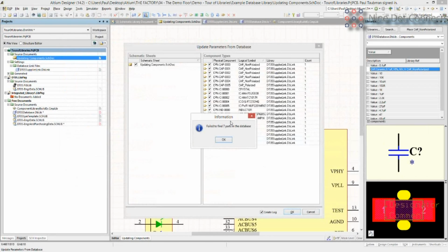The other 6 of them were resistors because my database library that I linked this to came from DigiKey. I don't know if you guys know this, but one of the cool features of DigiKey, and I think Mouser does the exact same thing, is you can give them a list. I took my company part numbers, the manufacturer's name, and the manufacturer's number, which I got from all the supplier links earlier on. I copied that into an Excel sheet and uploaded it into DigiKey. DigiKey told me the statuses for each of those parts, and then I downloaded an Excel sheet with all the additional information. I turned that Excel information into an Access database, and that's what this is pointing to right now. Interestingly enough, these parts that I found were from Mouser, and DigiKey didn't happen to sell them, which I think was unusual, but that's why 7 of these parts, 6 of which are resistors, aren't found.